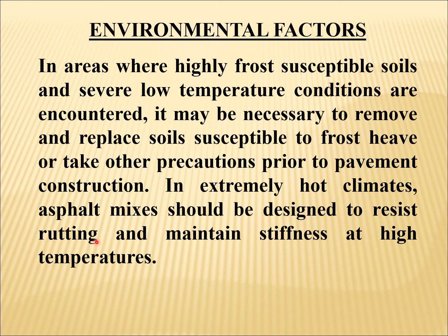Rutting is basically a defect in the pavement, and you can say because of the poor quality of the bitumen, sometimes we are having the continuous depression under the wheels of the vehicles on the road surface. So that is called rutting.